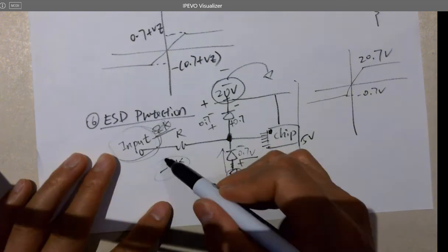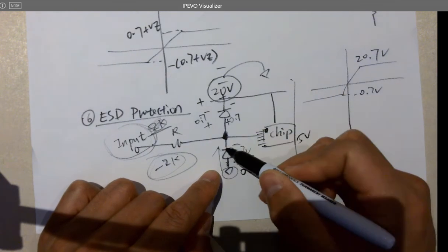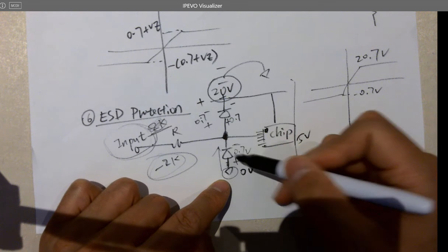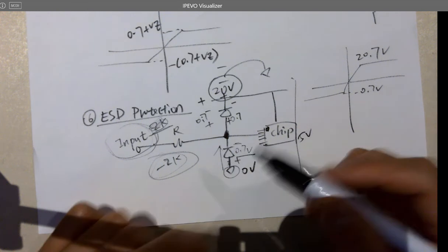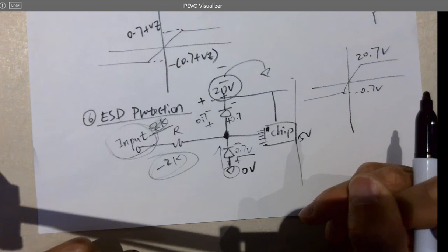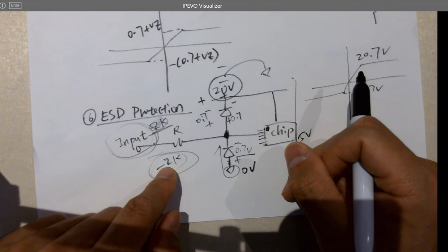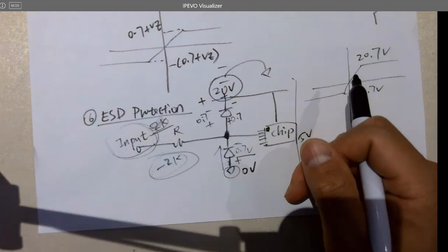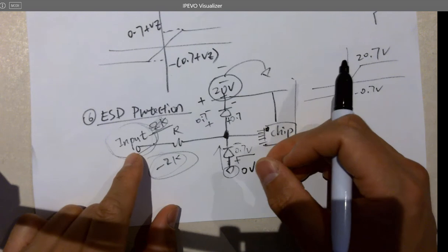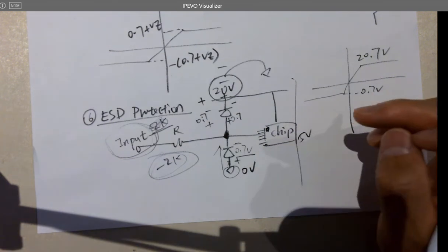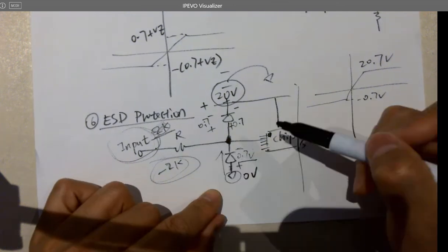You are thinking about negative 2000 volts being added to here. Why can this diode run all the current and drop the voltage? It actually pulls the voltage down to the ground, very close. But whenever it reaches negative 0.7, it just stops. So why is it able to do that? Because that 2000 volts is not a voltage source, right? It doesn't work like this one. This one is being plugged into the outlet. It's being supplied by the power plant. It is able to supply whatever current you need. This is not. You are not a power plant. It just has some charges. It's a pretty high voltage, but the current is very low. Whenever you discharge it, the voltage is going to decrease like crazy. So that's why it is able to be discharged really quickly.